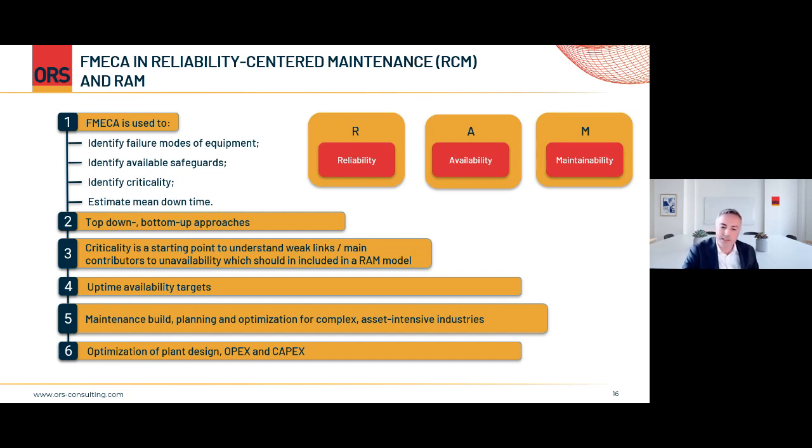And why is it important? Because these asset operators must understand and prioritize their resources for what we call maintenance purposes, and also in order to meet the uptime availability targets. First of all, they will have to select proper components with the given reliability and elimination of the failure modes. Thereafter, they will also need to develop the test procedures, also proof test procedures, select the proper test tools, and develop their maintenance programs. It could happen that some systems or components will be subject to preventive corrective maintenance, and some other systems will just be run to fail type of systems or components.